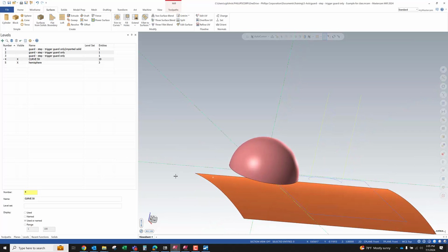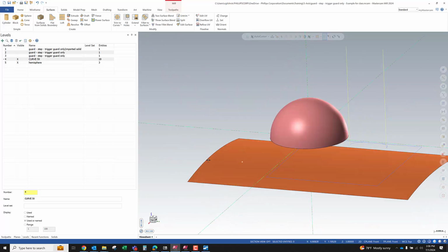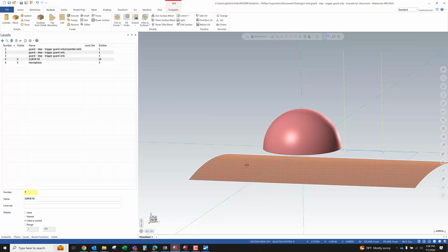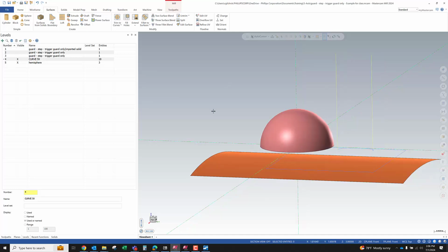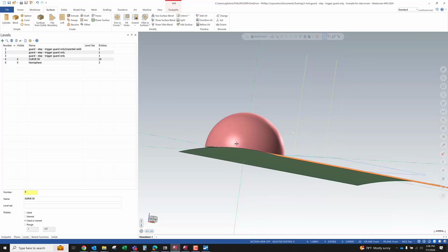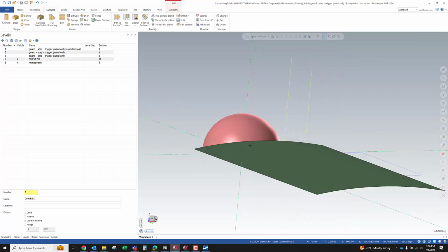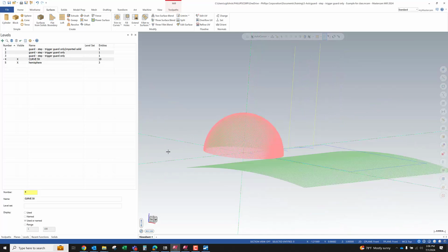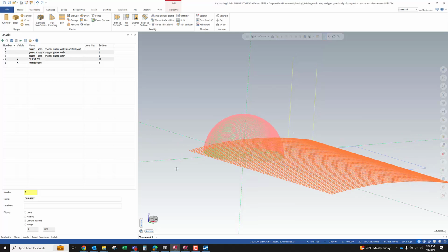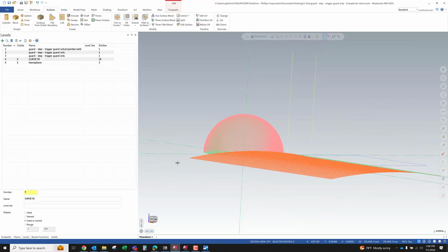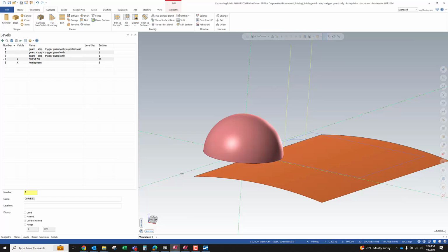If I look at this in shaded view, you can clearly see this is the top side of the surface. I click on change surface normal. You can see the normal's pointing up the right direction, right? You agree with me? Yep. This is the bottom. If I unshade, the unshaded display of the normals is reversed from the shaded display.